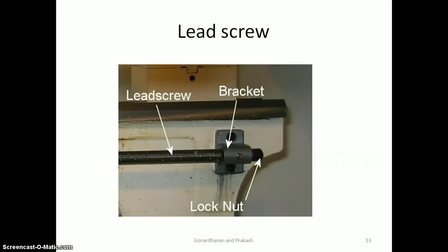The lead screw or screw rod is used for thread cutting operations. The lead screw is a long threaded shaft used as a master screw. It is used only when threads are to be cut. A half nut engages or disengages the carriage with the lead screw.